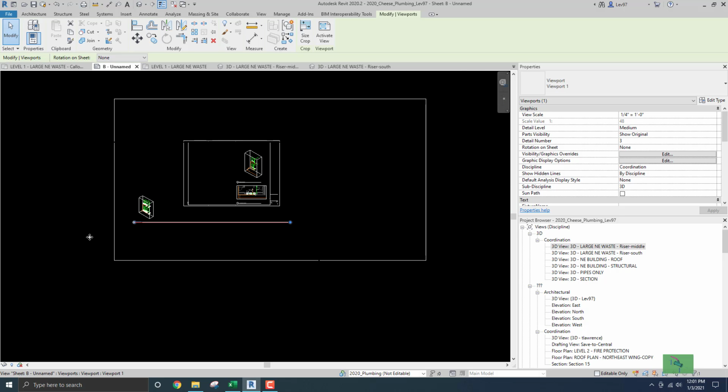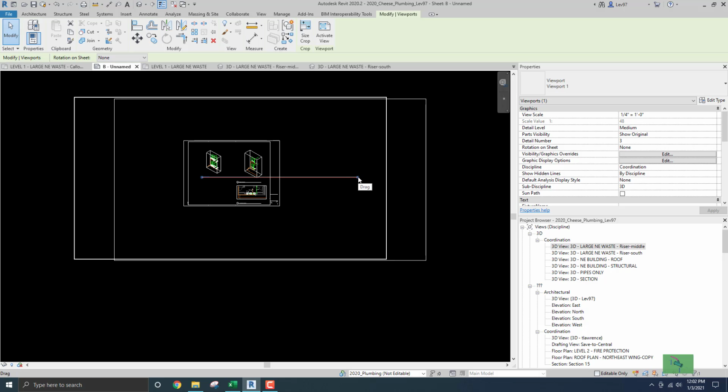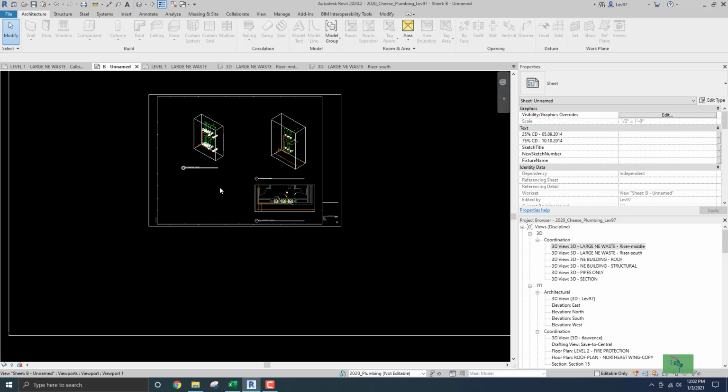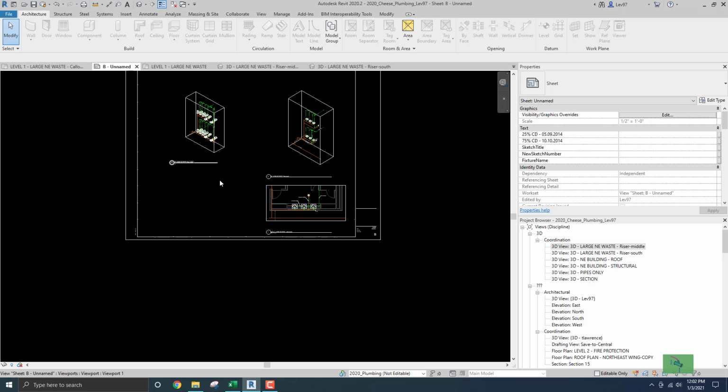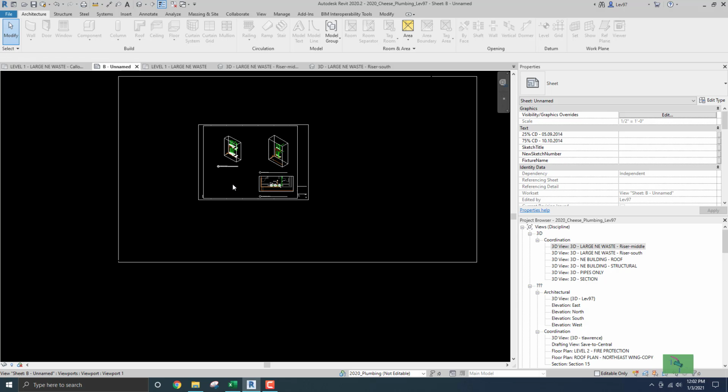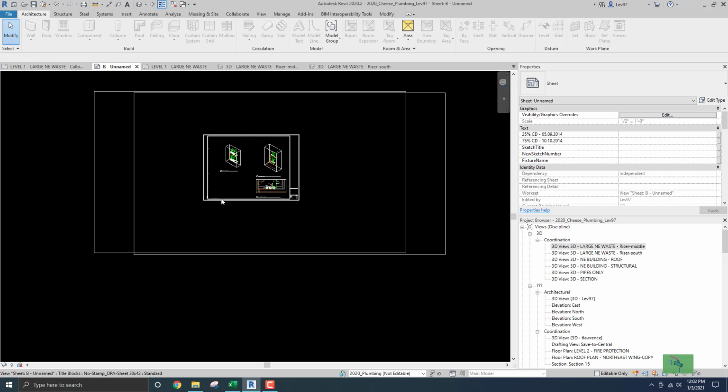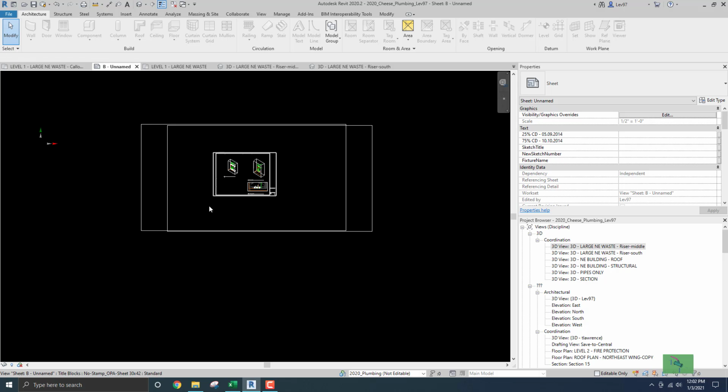Which is what I always recommend you do, is move your node from right to left, because there's no confusion with Revit if you're doing it like that. And once you have it highlighted like it is now, you can always go over and move it over. It usually works 9 times out of 10, or really 10 times out of 10, because there's no confusion. There's only one node. So we got that.